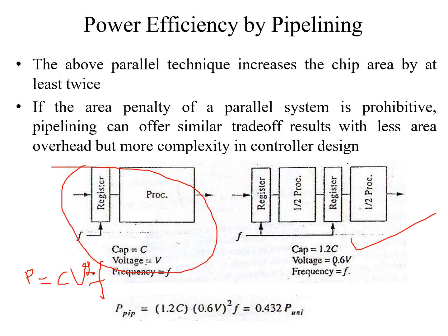So the glitches occur at the architecture level because many signals are given to the processors and the logic present in the architecture. Many signals and clocks are introduced between the glitch input and output. The glitches can be avoided by the use of parallel and pipelining processes. If it is a parallel process, 60% of the power is reduced. Similarly, if you take a pipeline, the circuit has more complexity because there is a control, but 54% of the power is reduced.